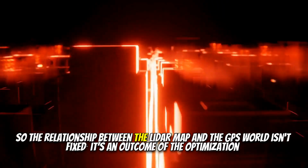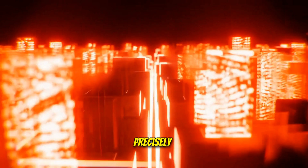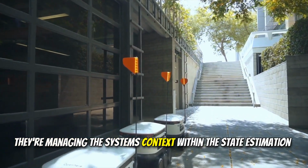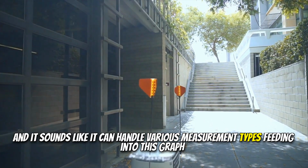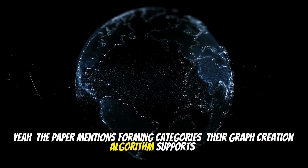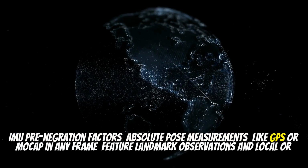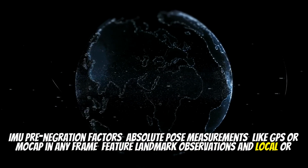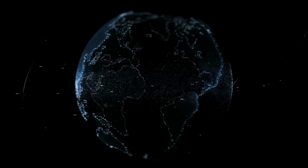So the relationship between the LiDAR map and the GPS world isn't fixed. It's an outcome of the optimization. Precisely. It's estimated alongside the robot's pose. They're managing the system's context within the state estimation. And it sounds like it can handle various measurement types feeding into this graph. Yeah, the paper mentions four main categories their graph creation algorithm supports. IMU pre-integration factors, absolute pose measurements like GPS or mocap in any frame, feature landmark observations, and local or relative measurements like wheel odometry or scan matching between LiDAR scans. It's built to be flexible.